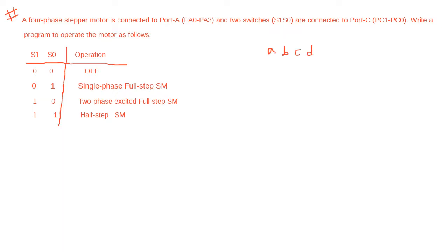So, the four-phase stepper motor system, and it is about the angle theta. We have to operate the motor as one phase first. For example, if A is 1 and all others are 0, it is at 0°. The reference axis is the A phase.